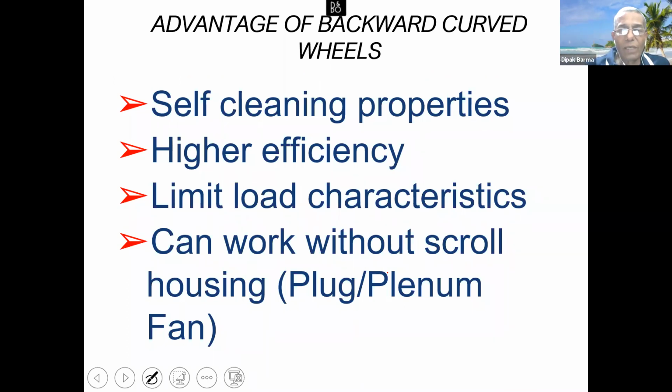It has self-cleaning properties. It has higher efficiency. It has a limit load characteristic. It will not get overloaded, and it can work without a scroll also. You place it in a housing, which becomes a plug fan or a plenum fan, and which can continue working, and cleaning becomes much easier once it is done in a housing. So the scroll need not be opened, the impeller need not be taken out. A person can go in and clean it. So that's an important aspect. That is where a backward blower is important.